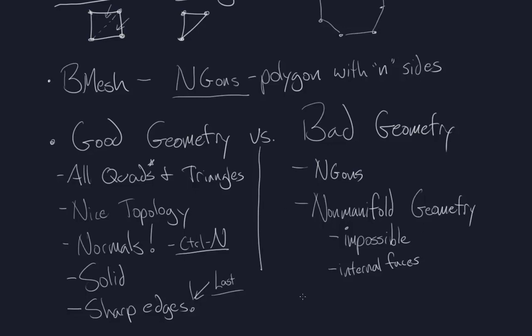And along with internal faces comes this. Doubled geometry. It's easy to make, especially in Blender. Actually, in Blender, it may be easier to make than just about any other program I know of. It's funny, too, because Blender has a remove doubles tool, which is specifically made for solving this problem. And I always kind of laugh because usually after I show it, one or two people will be like, "Man, I wish Maya had a remove doubles feature," and it turns out it does.